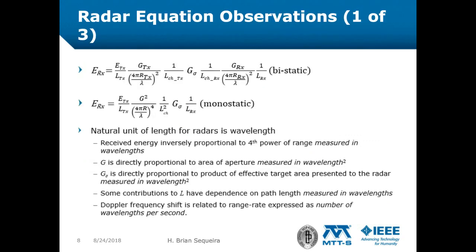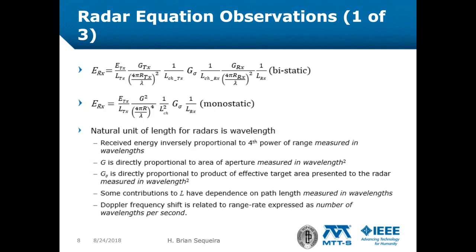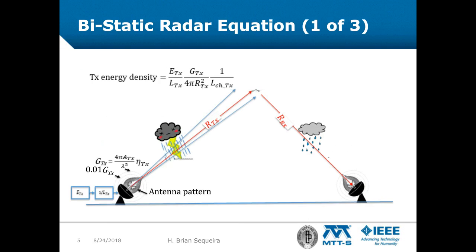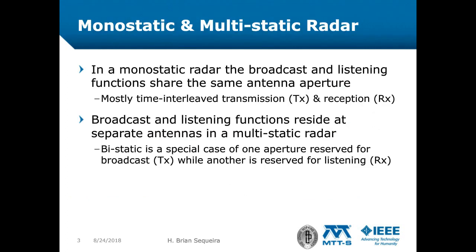This aspect of the computation is of increasing import in modern radars that operate in dense signal environments and in which spectrum is likely to be shared by a number of co-primary users, such as automotive radar-equipped self-driving cars that travel along a common highway. Among the threshold crossings that have the same pedigree, the radar may do additional computation, for example, to distinguish targets from clutter and multipath.